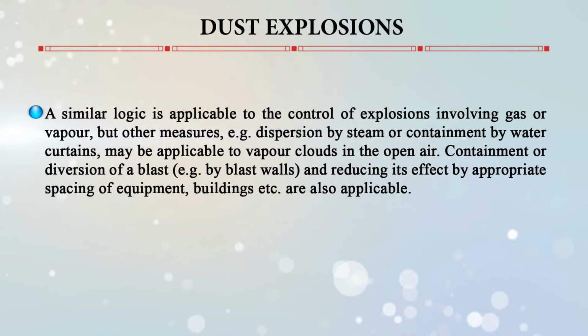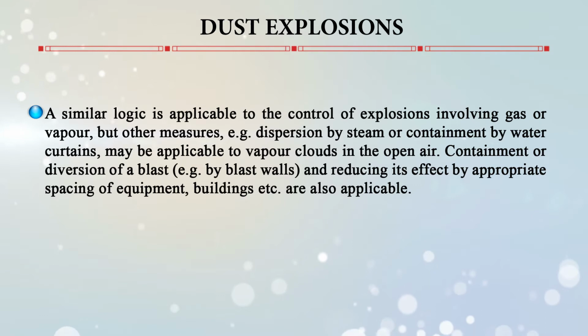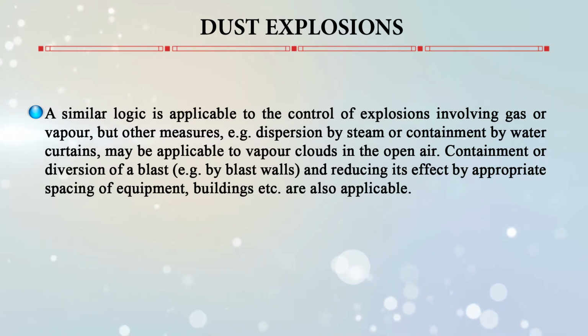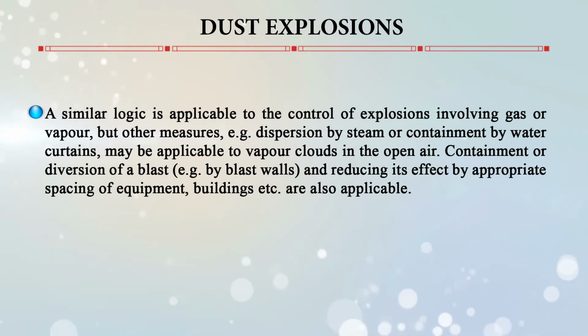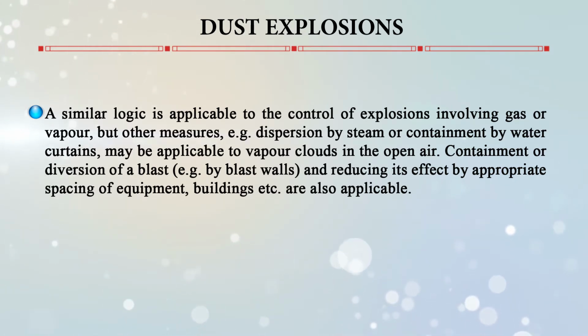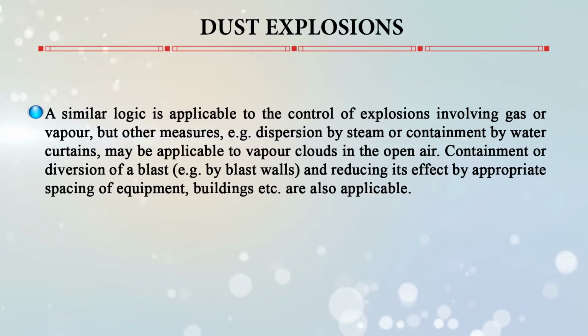They are also applicable to vapor clouds in the open air. Containment or diversion of a blast, normally by blast valves, and reducing its effects by appropriate spacing of the equipment and buildings, are also applicable.